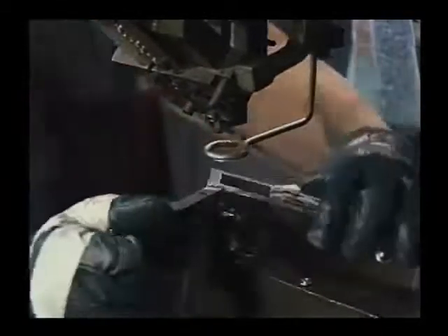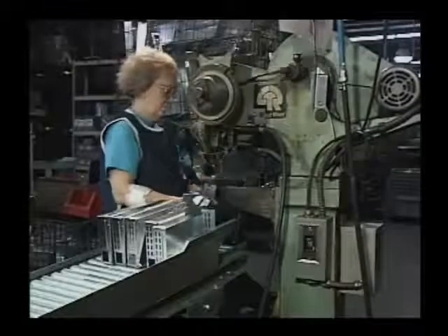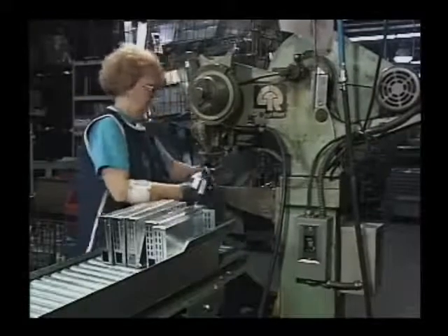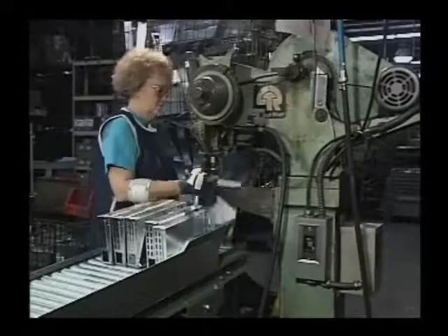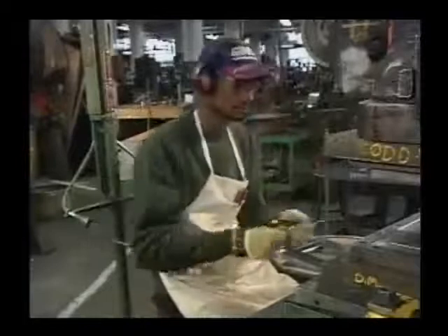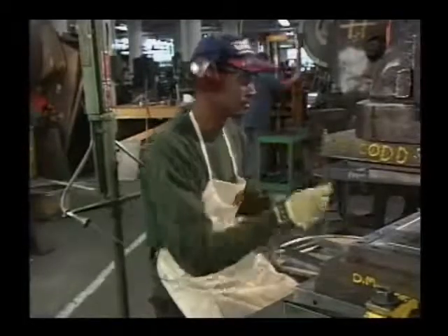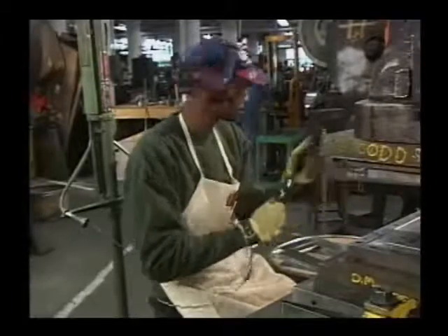One drawback of drop probe devices is that they only keep the machine from starting and do not stop the machine that is already in operation. For this reason, they must only be used on machines like small riveters that perform a single rapid movement each time they are activated.